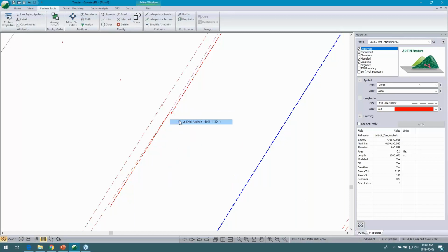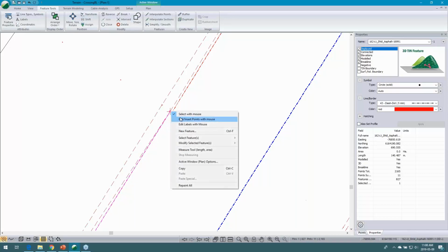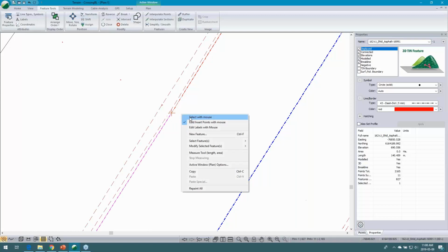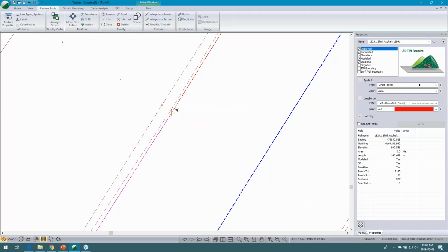We're going to grab the shoulder, and we're going to edit and move it over. Now if I go back into select mode, holding my shift key, I am able to hit Control J, or we can do that again up here, shift key, hold this, and select join. And that has connected those break lines back together.